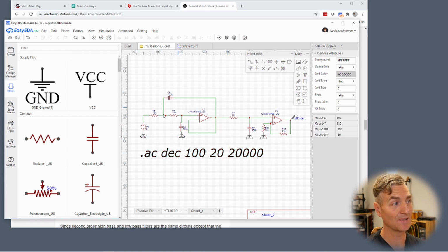So here's my filter. I have the voltage source, which is our audio input, going into a 10 kilo ohm resistor that has a feedback loop from a 100 nanofarad capacitor. That's our first low pass filter. And then we have a second low pass filter right here, another 10K, 100 nanofarad capacitor. We have the first stage of our filter set up as a unity gain. So we just have V out back to the negative side of V in on my op amp.